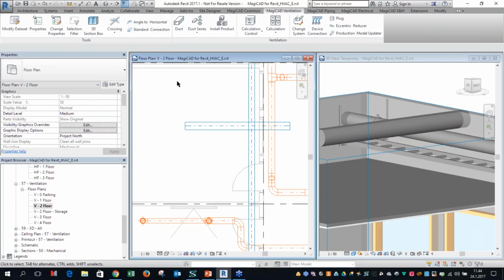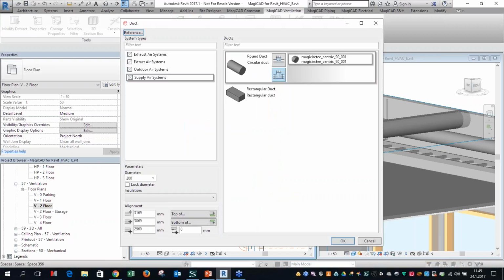It also understands, or recognizes, the insulation. If the duct or pipe is insulated, then it takes the height level from that. Yeah, and then one more thing here is the tolerance. So if you want to have some space between the objects, then you can define the tolerance here. And as you can see, it calculated right away.